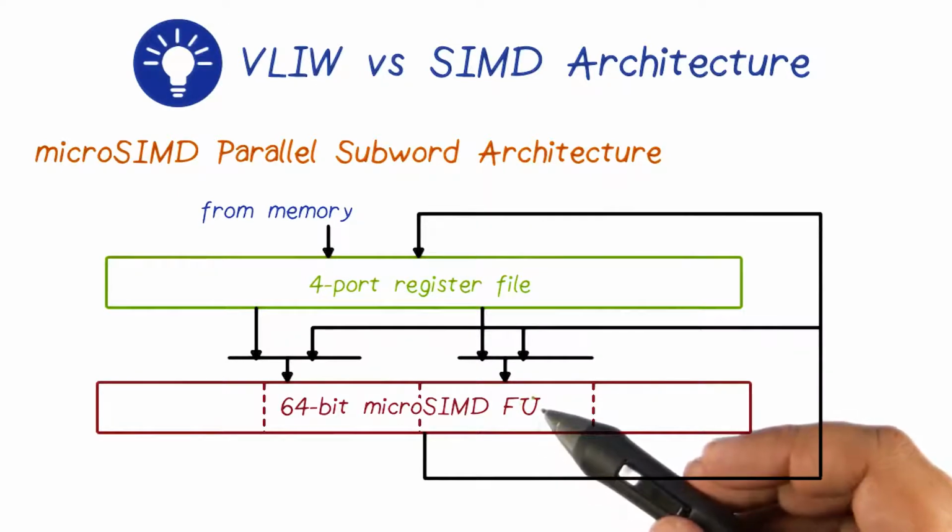So you can see that we operate here on subwords, that is within a word. We group those bits into subwords and we operate on those as one unit. Now if you do that, for example, for 4 16-bit subwords, we have a SIMD kind of processing going on there, but that SIMD processing is on a subword as against doing it on the full register.